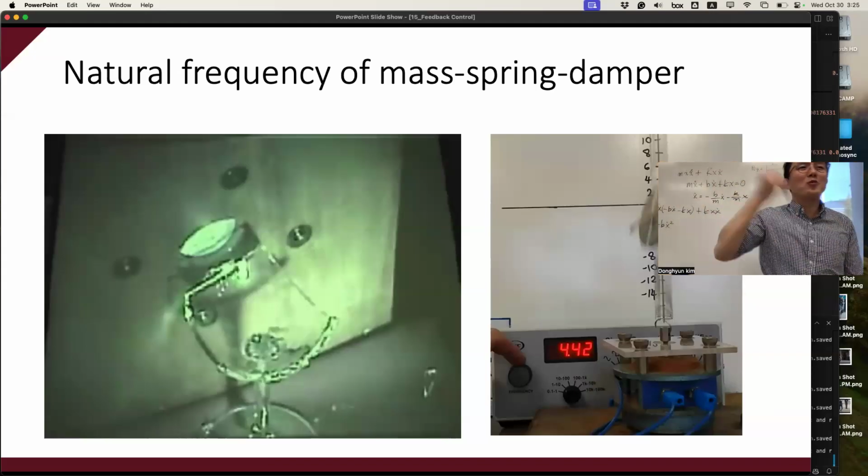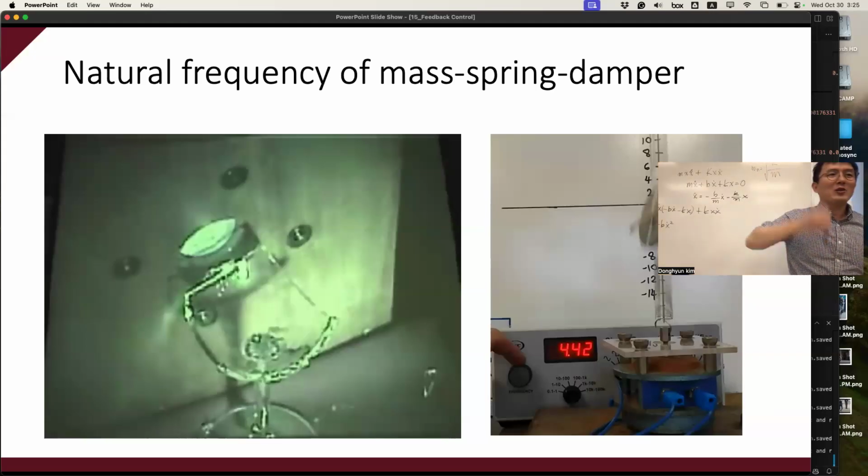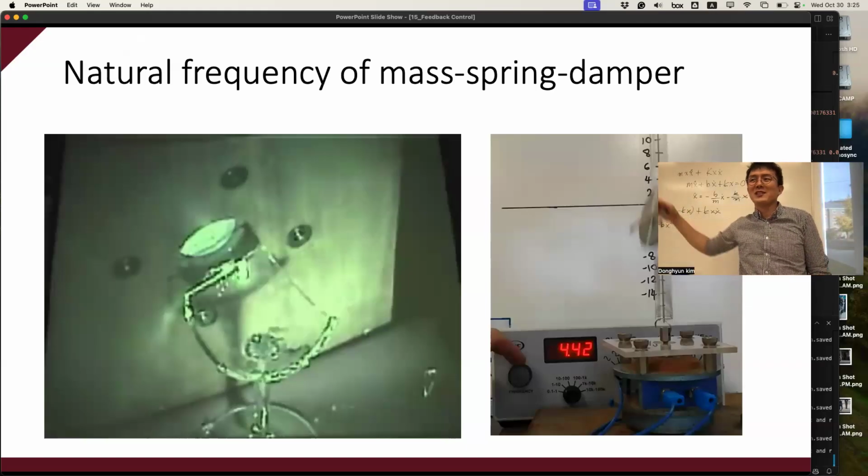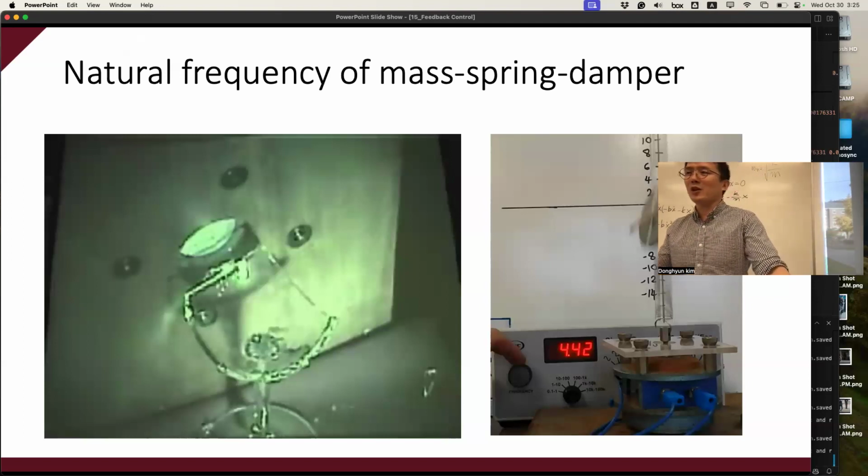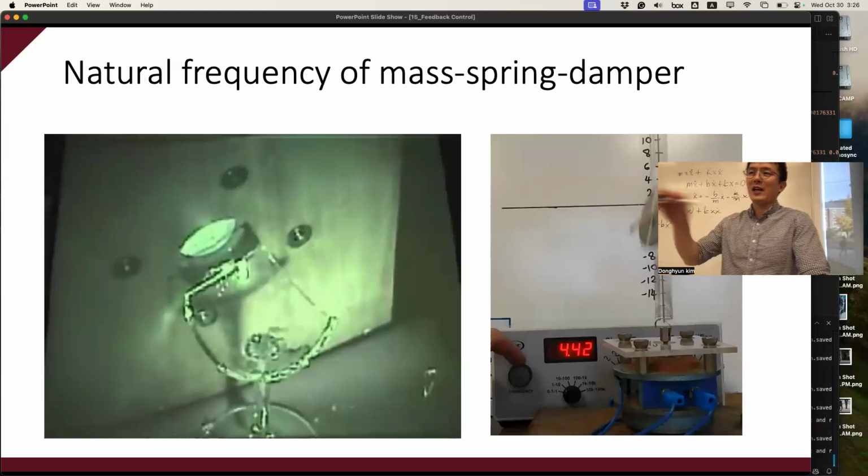So if you do this, then this frequency is about 3 Hertz. The natural frequency of the steel is way above 3 Hertz. So then it's hard to excite that system. There is a way to make this steel and all that kind of thing excited. So you can actually touch the natural frequency of a certain system made with steel or a more stiff material. How? Increasing the mass. So even though you have a really stiff bar, if you put on a really large mass, then you still can see oscillation. So it's a kind of robot design perspective.